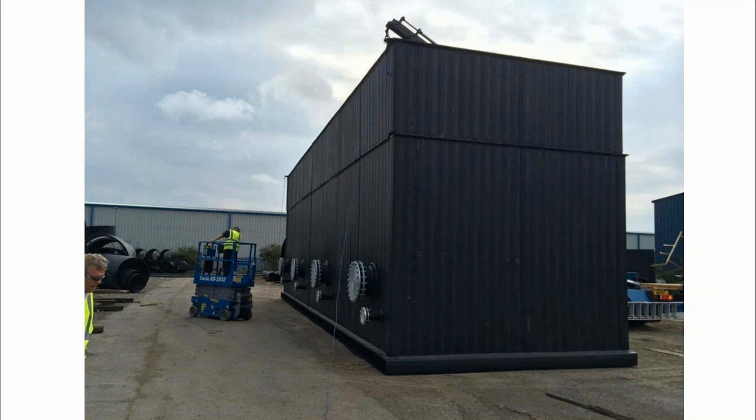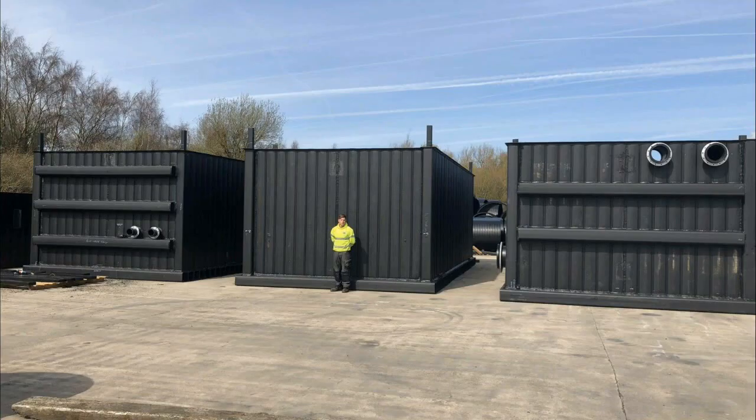This is a TSS particle settling and pre-treatment structure that has internal baffle walls, controls, and hopper bottoms to remove larges and settleable solids. We can also do outlet control structures for stormwater ponds or inlet control structures as well. And these particular structures have internal weirs and orifice control to regulate flow under gravity head.